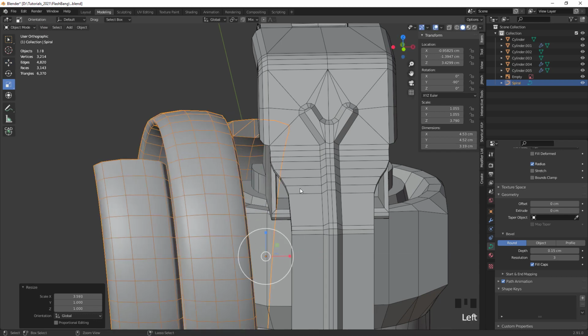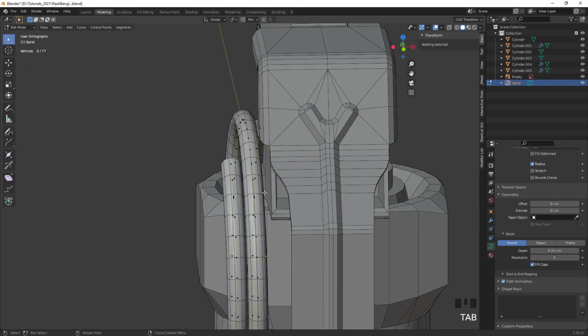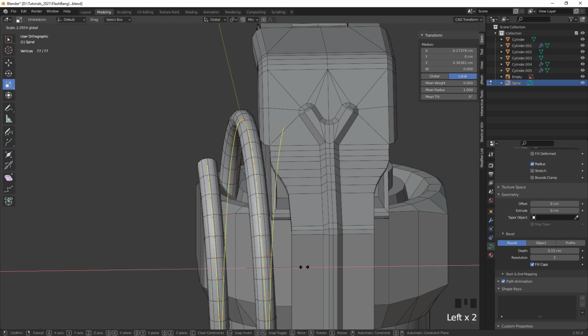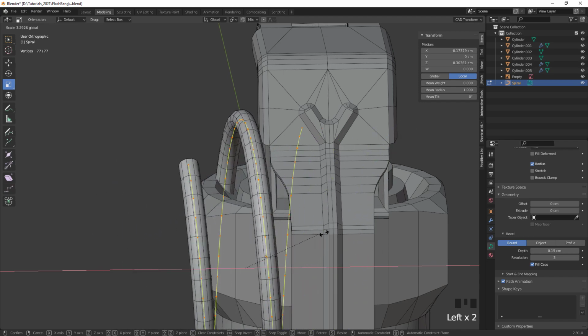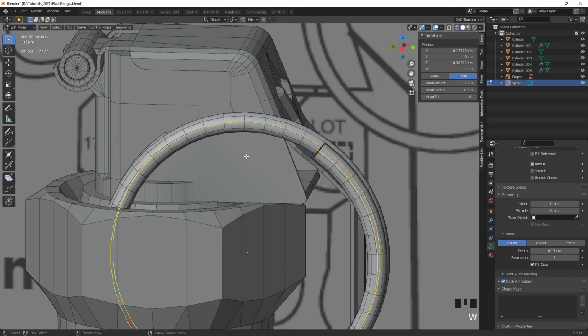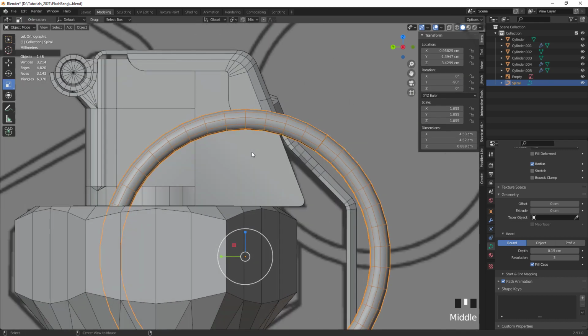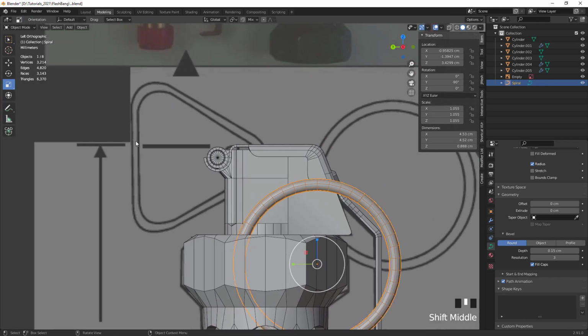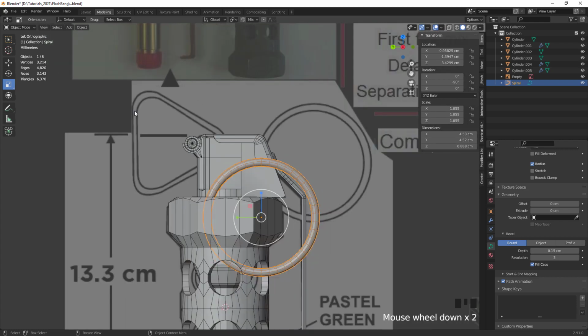By the way, if you scale it like that, it will deform. But if you select only these edges or these curves, you can then scale it and it will remain the same depth. So that way we can always edit it later on. But we don't actually have to do that in that case. It was fine as it is. Just wanted to show that.